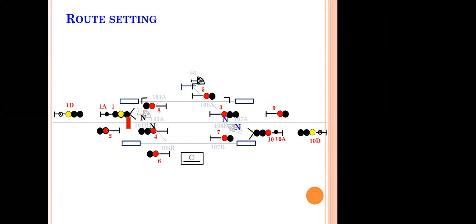When the train is approaching a signal with high speed from the block section, I need to consider the overlap because, for the reasons mentioned yesterday, the train may not stop at the starter. For that purpose, I need to maintain the overlap. I need to satisfy the overlap. For other signals, the train is starting from here, no problem. It is starting with zero speed. I can give only the route, no overlap is necessary.